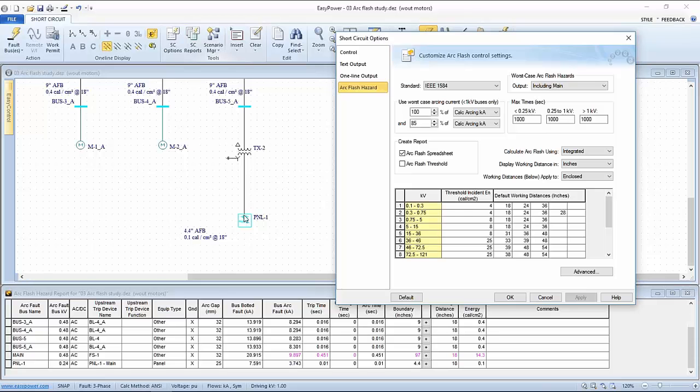Is that fuse really outside of the plasma reach if I have a fault just upstream of the fuse? Again, I can't make that call from here, and so I'm going to go with the assumption that I probably can't do that because the fuse is probably inside the panel and I'll be staring at it when I'm trying to work on the hot bus.